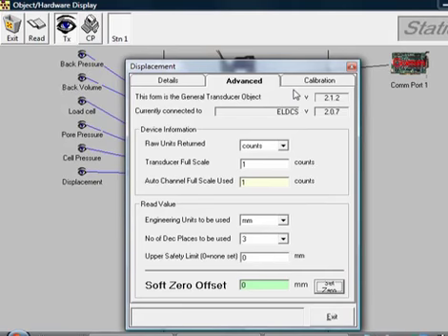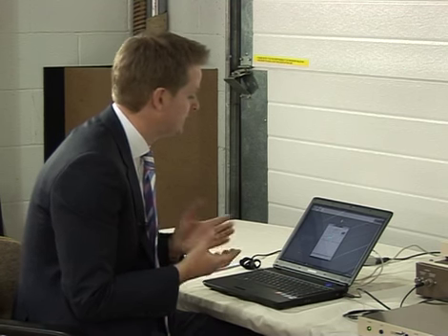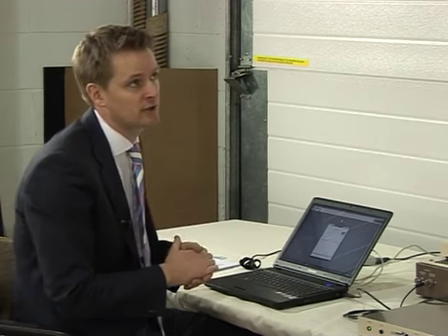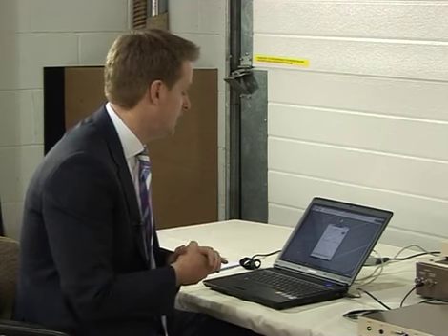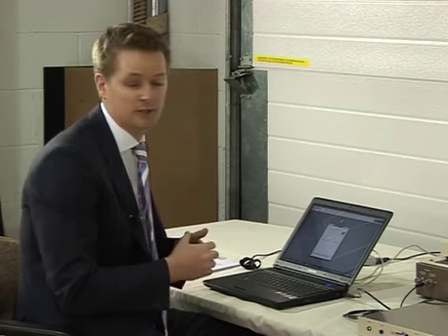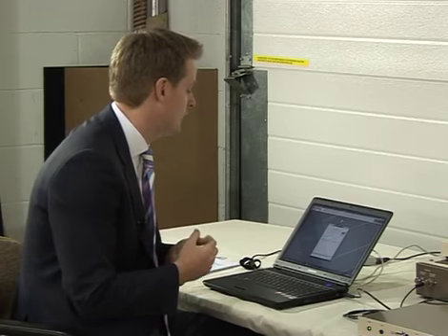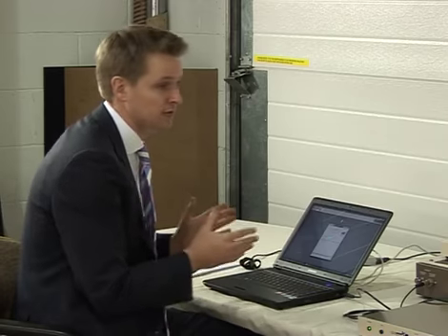The important value is the sensitivity for the encoder. For the ELDYN machines, this is 0.000208, which is a figure that's calculated from the 6:1 ratio of the drive and the number of lines on the encoder. But your system will be supplied with a calibration certificate for the encoder, so check that in case it is any different from my example.